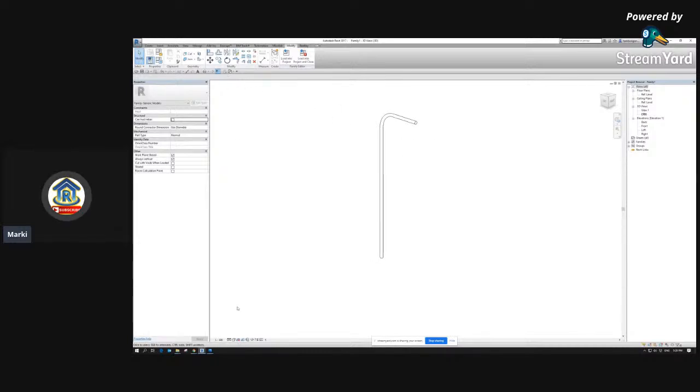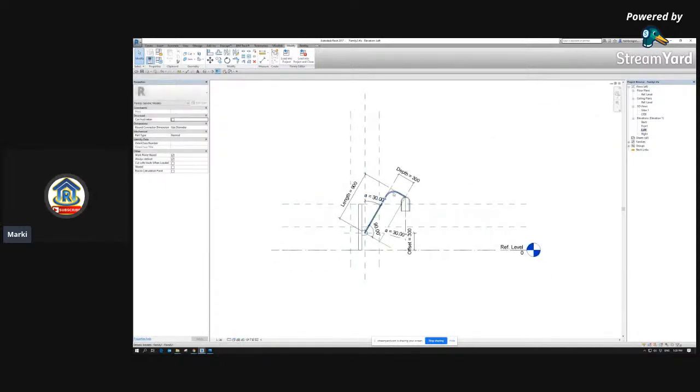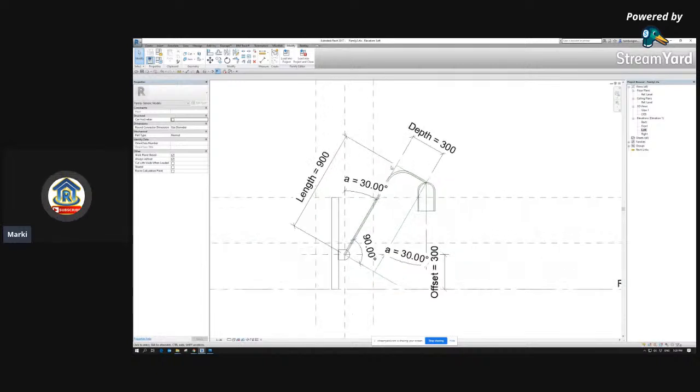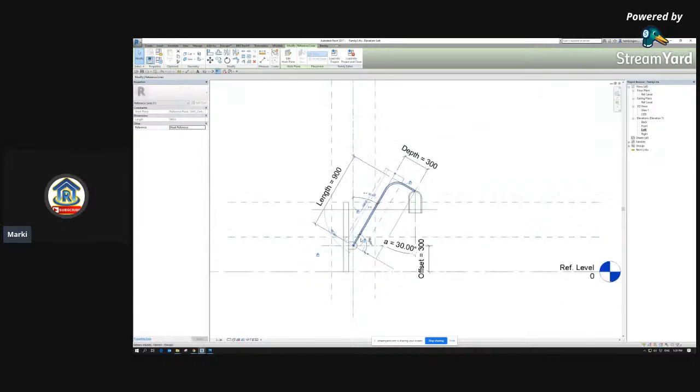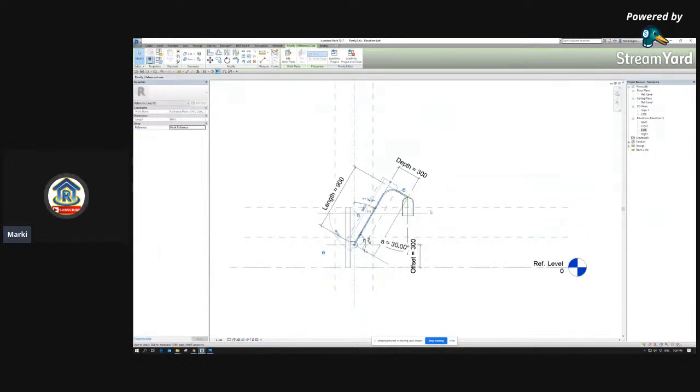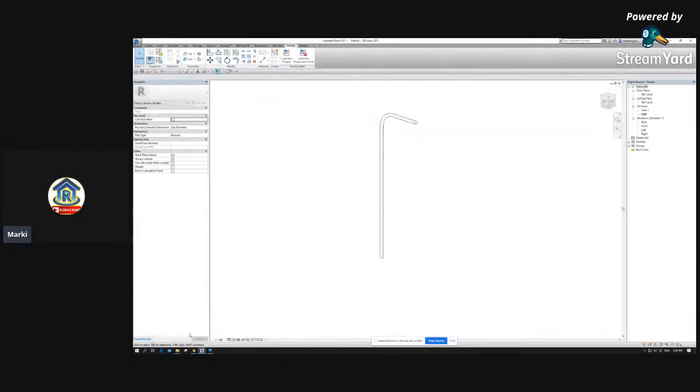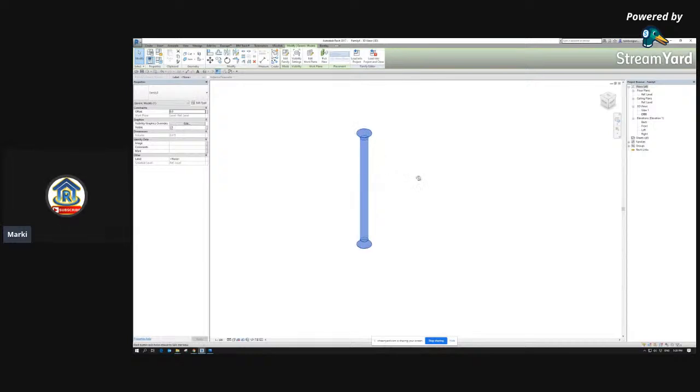But in reality, the family that you have to build is not really directly upright, because we have to understand what will be the host of our family. So in this study, I have the host of this reference line, which is the one that will be controlling the angle of all of this element. So now we will do this family in this new Revit model that I did, which is this one. I nested the post in this family.